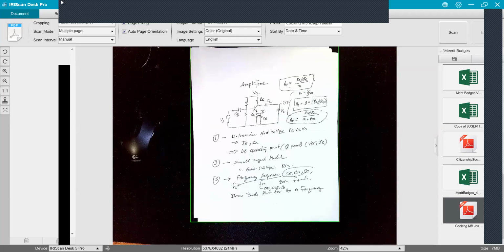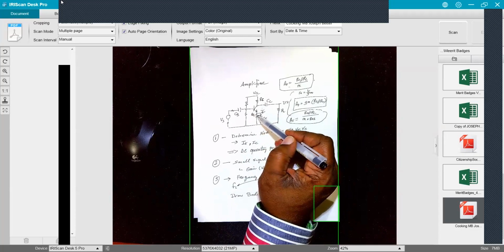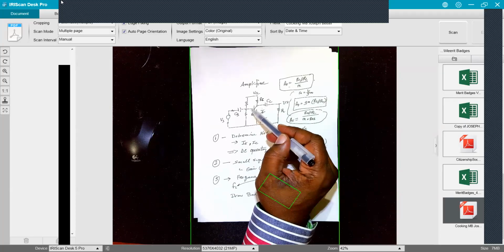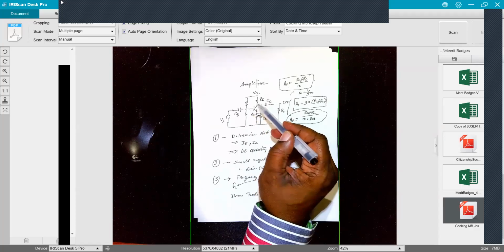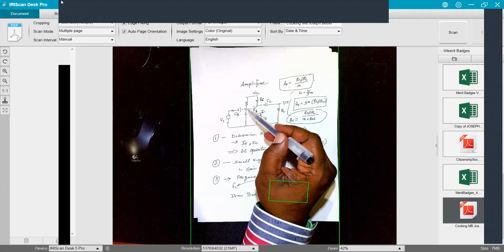That's something that when I took this class, I remember Dr. Davidson always harping on: always assume that you're operating in the active region, and then verify that you're operating in the active region. Active region is basically the base is greater than the emitter by 0.7 volts. We know that. If that's not true, then the transistor's not on. But also, this voltage here cannot be more than 0.7 volts higher than this one. If it does, it pushes this guy down, and this diode right here actually starts to conduct. And so we're not acting like an amplifier anymore.